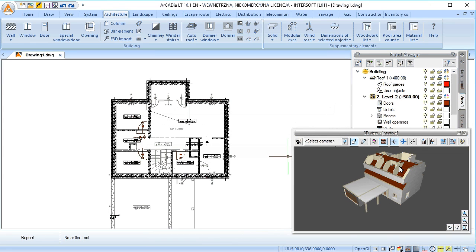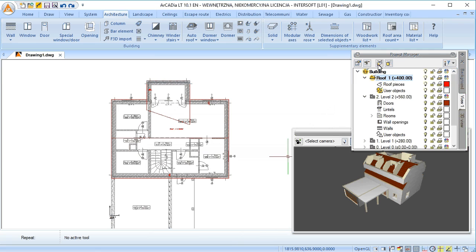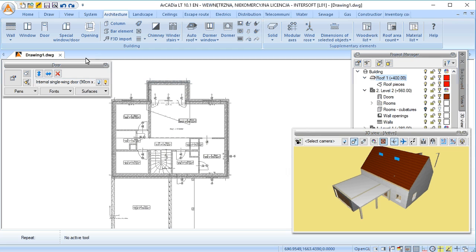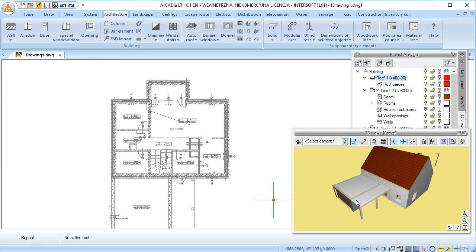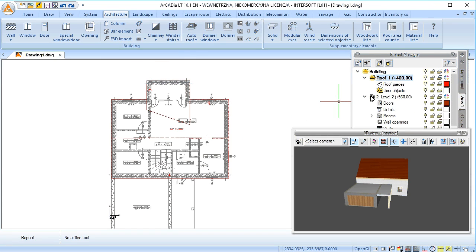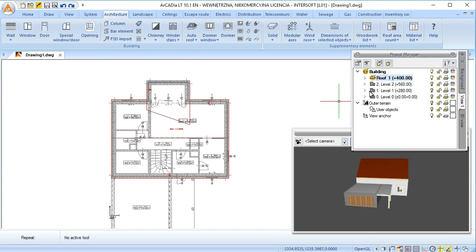To cut the inserted walls, we are clicking the icon before the name of the roof, and from the available icons, we are choosing Cut Objects. We are activating the 3D view by double-clicking on it in order to select protruding elements and delete them. We are double-clicking next to our drawing, thus activating the View 1 tab from the Project Manager window.